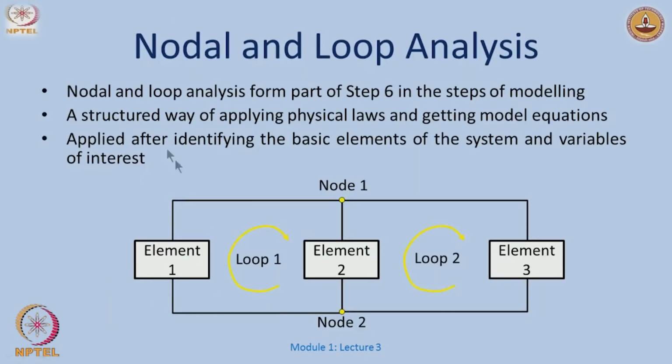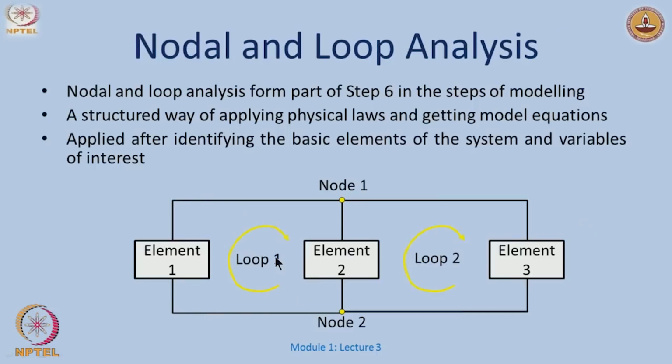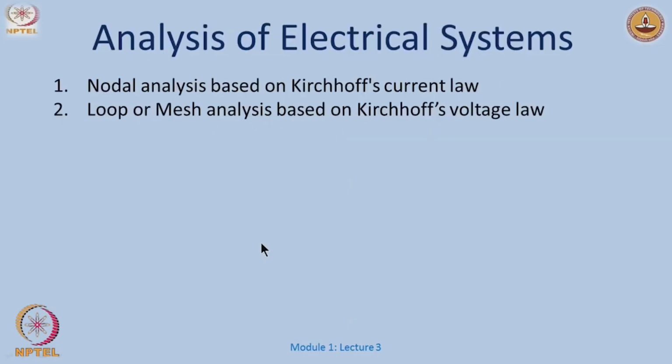Okay. So, again, coming from basic circuits, we all know what the nodal and the loop analysis are, and these are essentially coming from the physical laws. Whenever we do nodal and loop analysis, we apply in the context of circuits either Kirchhoff's voltage laws or the current laws and so on. So, once we identify basic elements, we interconnect them in a certain way which defines the circuit, and then we write down the relevant equations. Okay. So, the nodal analysis, as we know, is based on the current laws, and in the loop or the mesh analysis we write down the voltage laws.